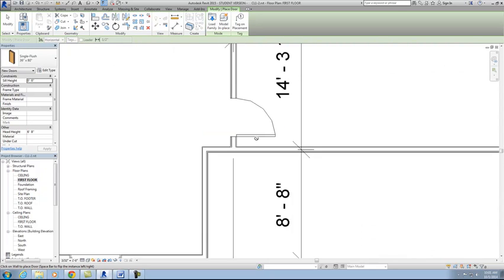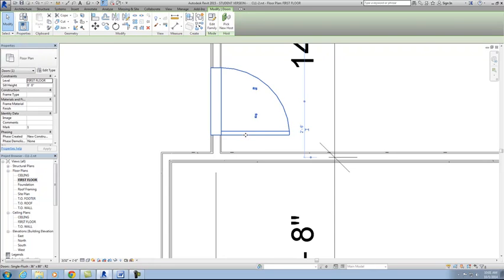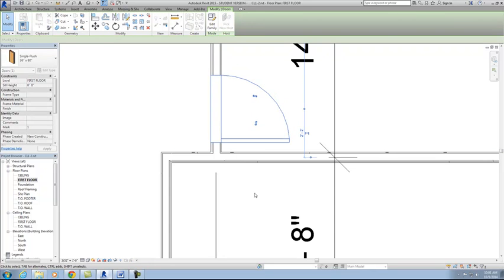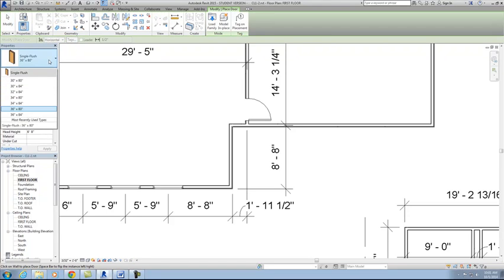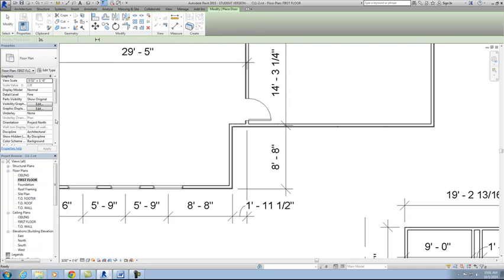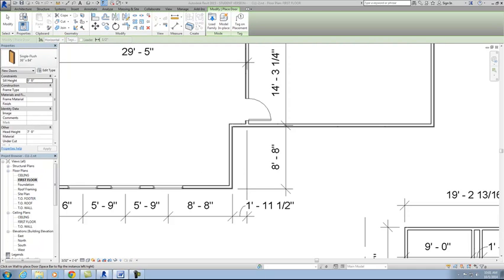And we're not going to worry about dimensioning this. I'm just going to make the hinge about a wall thickness. And then door C is going to be 36x84. So we go back to door, set this to 36x84, and then we'll add the door for this opening. You have to kind of move the mouse around until it swings the right way. You can also hit the space bar to swing vertically, change that distance as well. There we are.